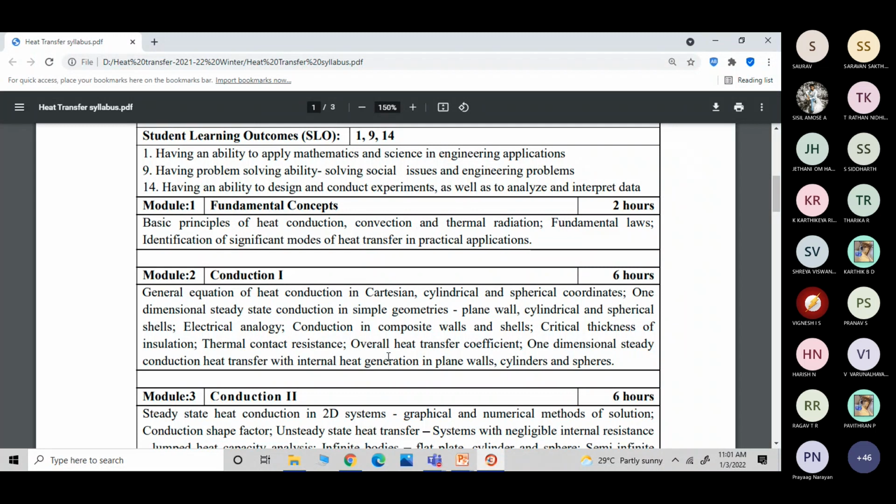So due to the flow of electricity, heat will be generated. That internal heat generated has to be dissipated out. If it is not properly dissipated, as some of your friends said, during summer the outside temperature is also higher, and due to improper heat dissipation during summer, usually the cables burst out.